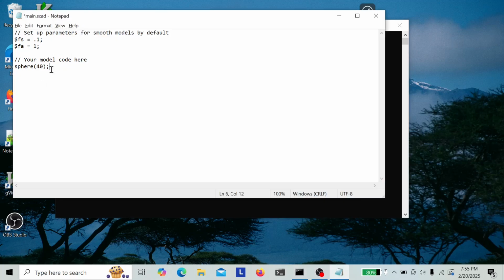So now I'll open the model and delete the sphere. Now I'm going to explain each model that I'm going to add, but I'm also going to read the whole thing afterwards, so you don't have to remember it. So first we're going to create a cube, and it's got a width of 10, a depth of 10, and a height of 10.